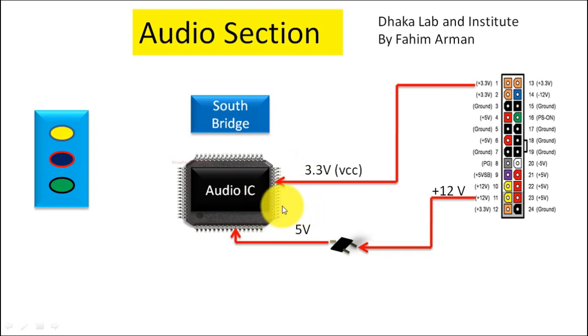These voltages are very important to power on this IC, and then the audio IC will communicate with the south bridge, and it is very important. The communication is very important, and communication will be successful if the south bridge is good and the audio IC is good.